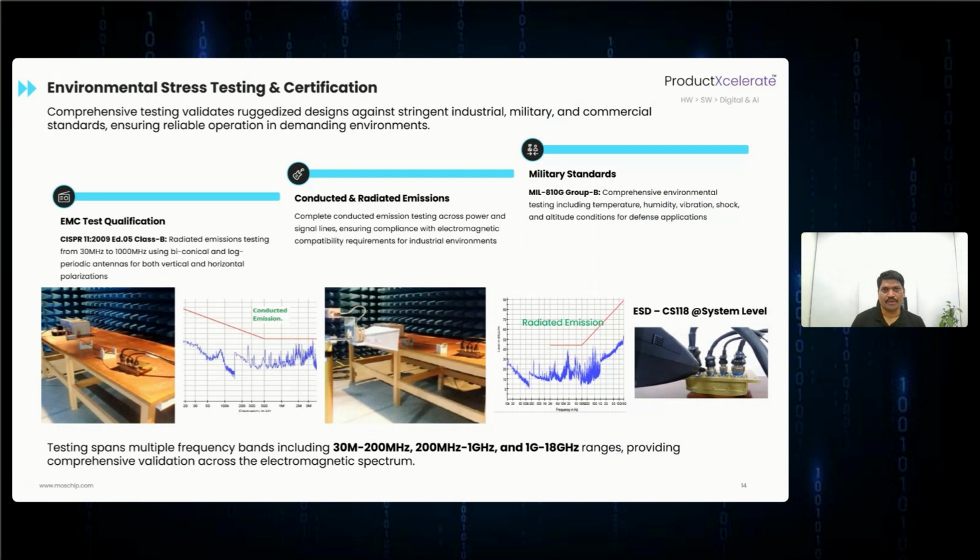As you all know, engineers often spend months addressing complex EMI/EMC compliance challenges for products, which include conducted emission and susceptibility, radiated emission and susceptibility, as well as HBM and CDM ESD evaluations. Design is only half the journey. The other half is proof that it survives reality. We carry out CISPR 11 and 32 Class A and Class B emissions and humidity checks for all the ISM and ITE products we design.